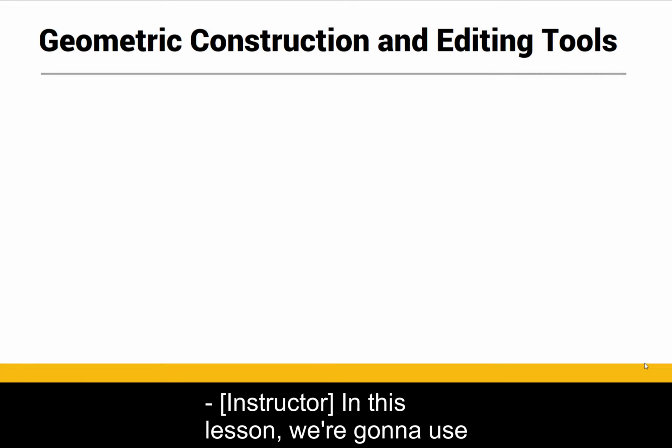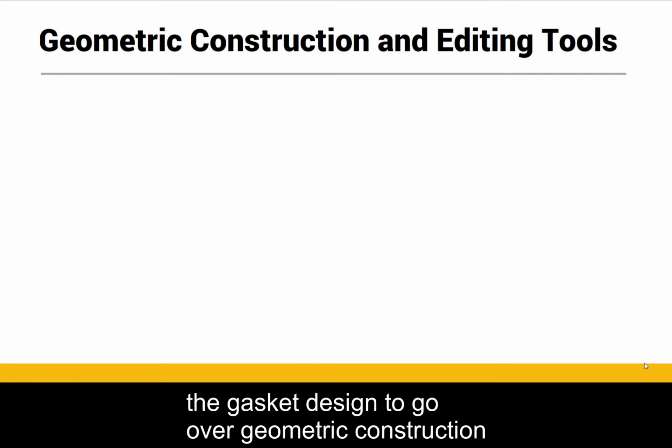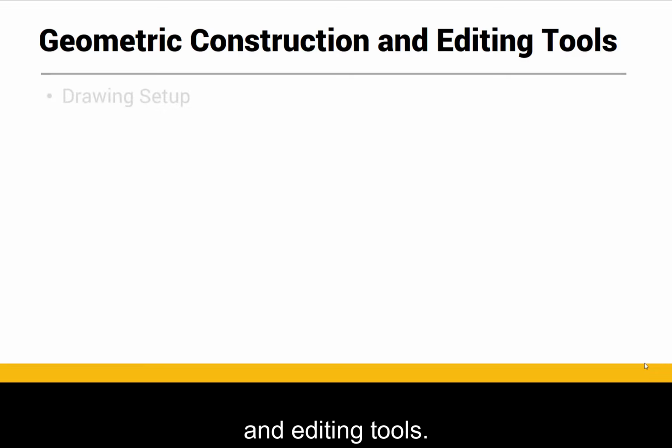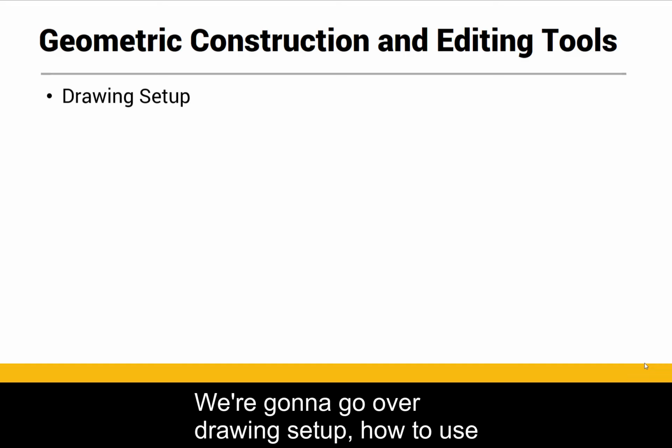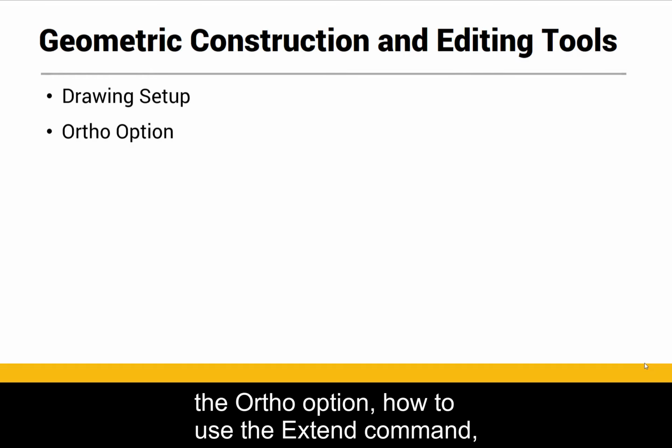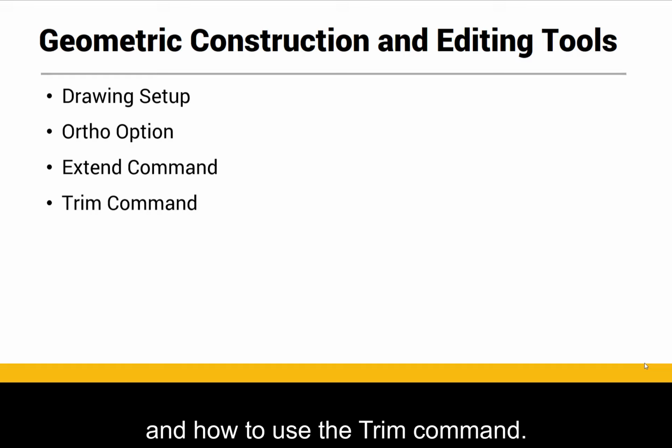In this lesson, we're going to use the gasket design to go over geometric construction and editing tools. We're going to go over drawing setup, how to use the ortho option, how to use the extend command, and how to use the trim command.